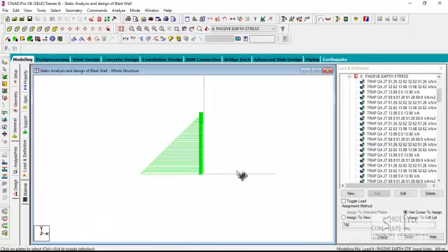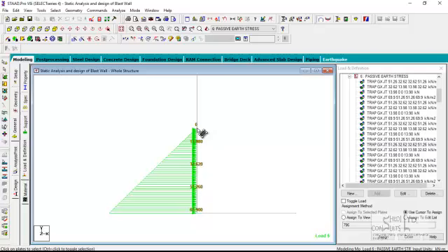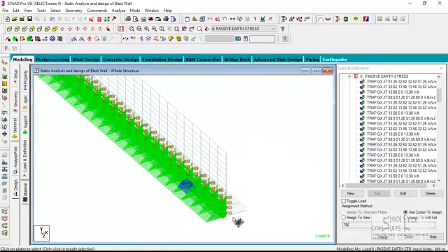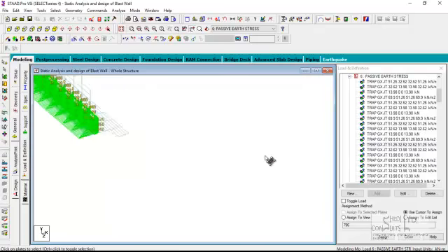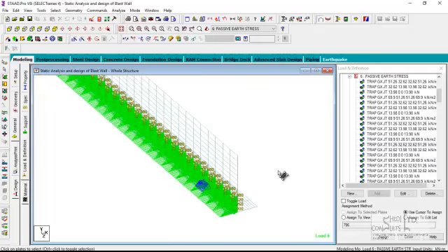If we look carefully, we'll see that the passive earth stress varies from 0 at the soil depth of 0 to 69.9 at the soil depth of 1.5. So the founding depth of the foundation is 1.5. 1.5 is a result of the DEP requirement that the depth of a blast resistant structure will be such as to prevent a continuous build-up of pressure, an increase in dynamic air pressure, in the event of an explosion. So in the event of an explosion, there's a potential for an increase in dynamic pressure if the founding depth of the foundation is not suitable.